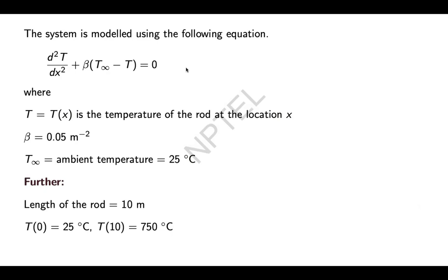Another thing you have to observe is that in earlier classes we have seen ordinary differential equations, but this is a second order ODE. Though we have not explicitly done it in the recorded lectures, during problem solving we had done two questions where a second order ODE can be converted into two first order ODEs and solved using an ODE solver like ode45 or ode15s. You should carefully convert the second order ODE to first order ODEs and use the inbuilt MATLAB solvers to solve it.